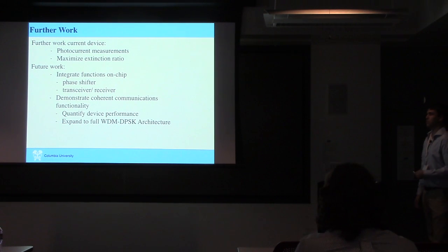We've been doing work, and we were able to do some finite difference time domain simulations, and showed that if we delay one bit from the other, then interfere them in this ring, we can actually back out an amplitude modulated signal for direct detection. Once we can show this on a single device, we want to expand it to a full, more systems level solution, where we have many of these devices lined up, and we can take a fiber with many signals and multiplex or demultiplex them.